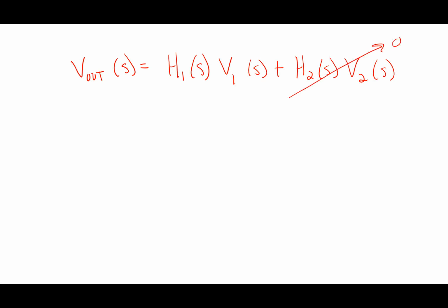It goes away, so it should square up with what I get. It's whatever component I get for V out when V1 is on. Then if I do the opposite, setting V1 to 0, I get that result. You get the same result either way, because you're really just doing a math trick when you do superposition.